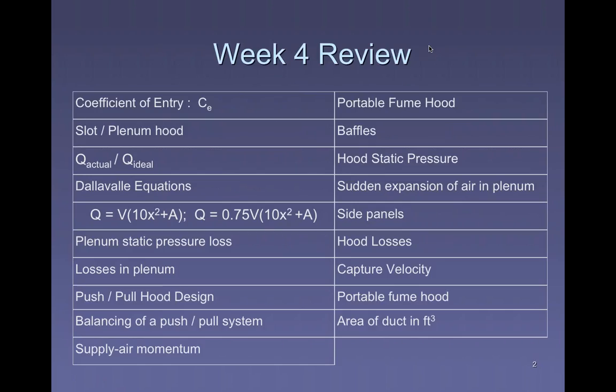Okay. Let's talk about this. This is some of the formulas that we went over before. Coefficient of entry is kind of like, as far as I'm concerned, a throwaway. It's basically the efficiency of the hood. The real thing I'm interested in is the hood entry loss. How much suction do you have to have, and how much energy do you lose pulling air through that hood? Because the hood entry loss tells me what the static pressure of the hood has to be at the point where you connect the ductwork to it. That's where it tells me what I need to produce with the fan, right, in order for this hood to work the way I want it to.